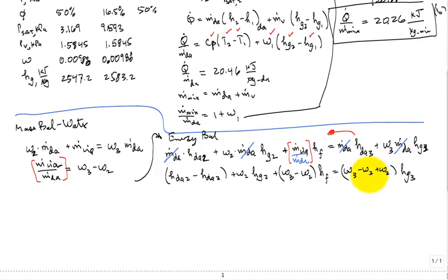Okay. So what we do is take this term and shove it over to that side, and then we take this term and take it over to the other side. So it doesn't change our change in the enthalpy of the dry air, and we can write that as Cp of the dry air times temperature 2 minus temperature 3 for the dry air.